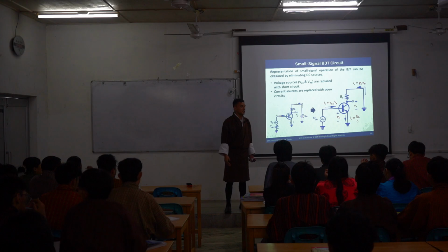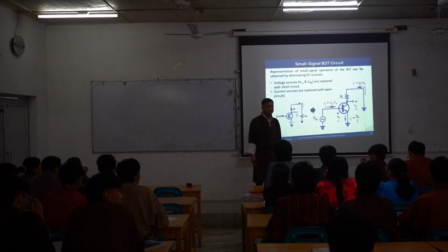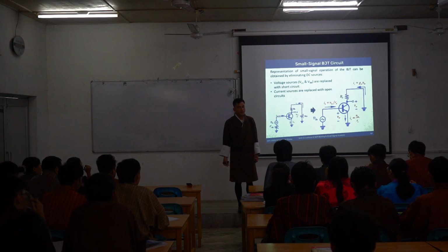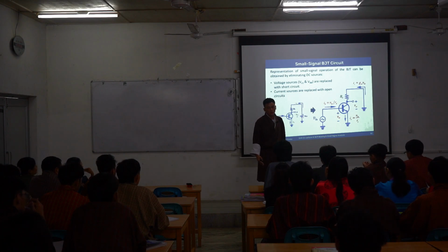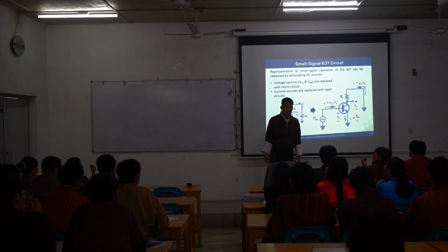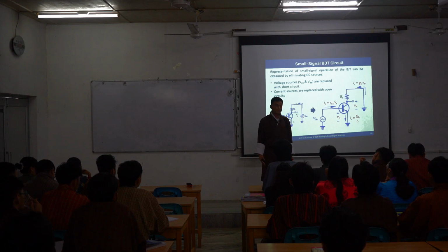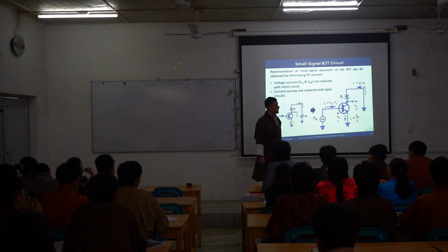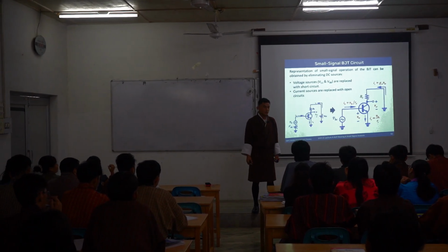When you perform the AC analysis, short circuit all the AC voltage sources, and open circuit the current sources. And if there is a capacitor, just open the capacitor. You need to be very careful with this. If you fail to do this, I am 100% sure that your analysis part would be zero. So we have done some calculations, firstly starting with the IC,